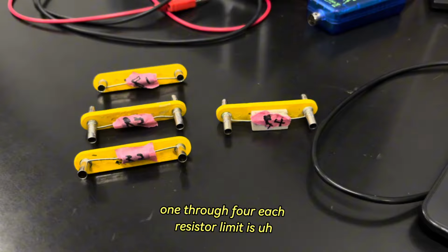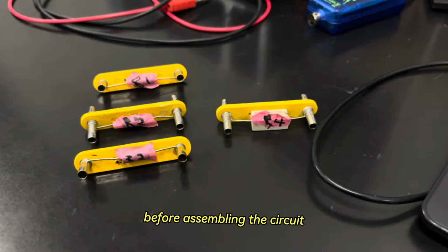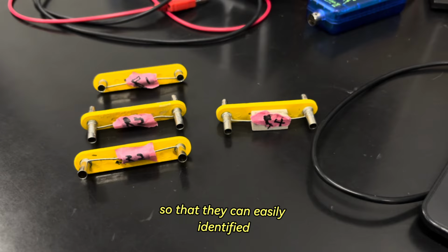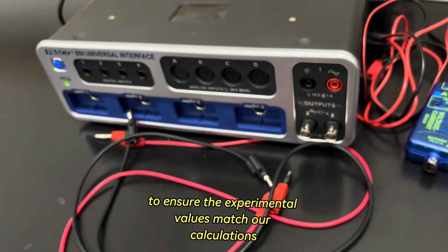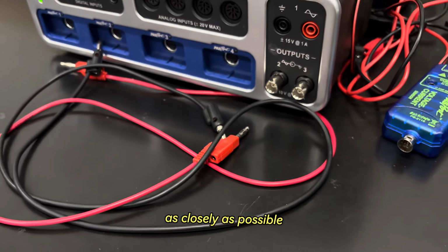Each resistor limits the flow of electric current through different paths of the circuit. Before assembling the circuit, each resistor is labeled using small pieces of tape so that they can easily be identified throughout the experiment. The actual resistance value of each resistor is measured using a multimeter to ensure the experimental values match our calculations as closely as possible.